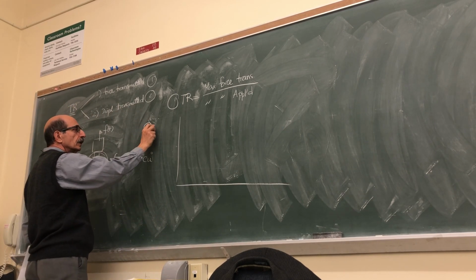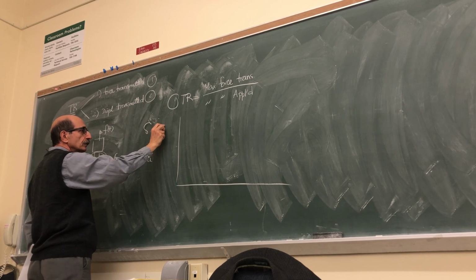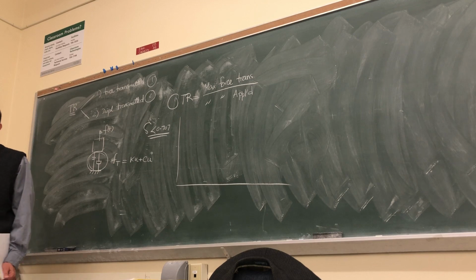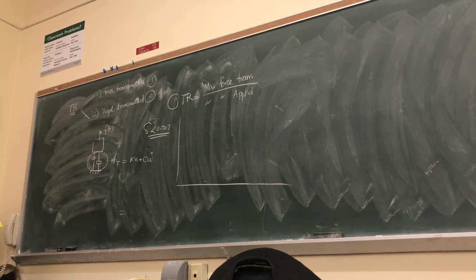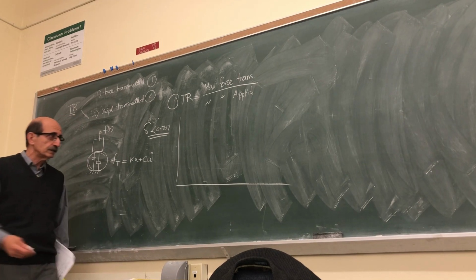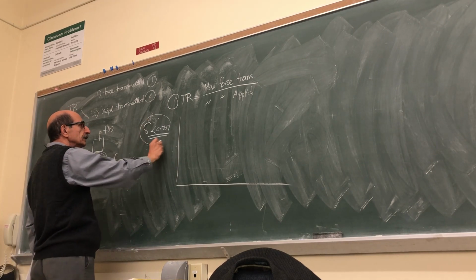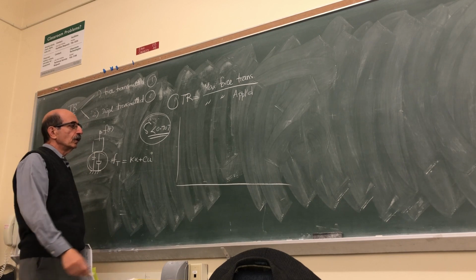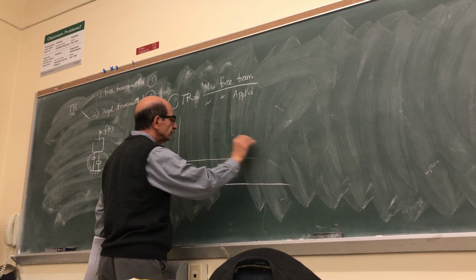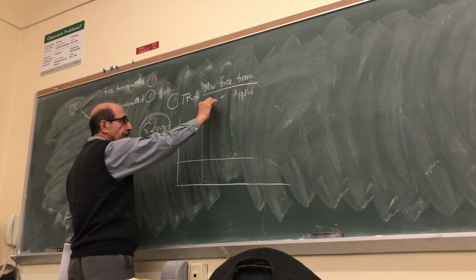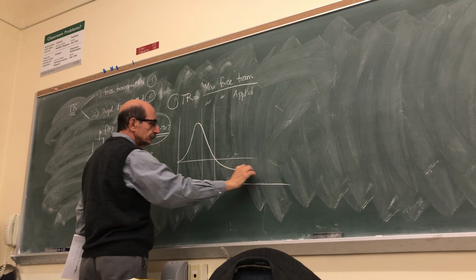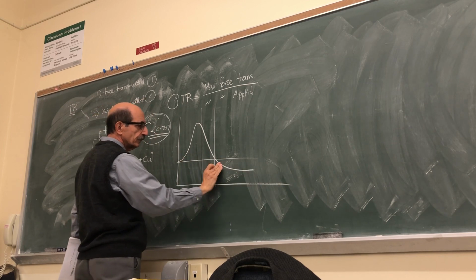case that zeta is less than 0.707. Because if zeta is greater than 0.707, we know that the maximum dynamic displacement will always be less than the static displacement anyway. So we don't care about that. This is the case that we are concerned and want to know within that range what happens. And this is for the force transmitted. As we saw, we had basically something like this.